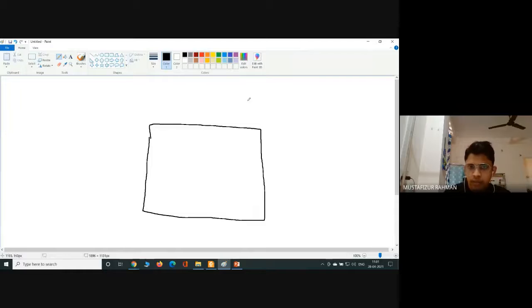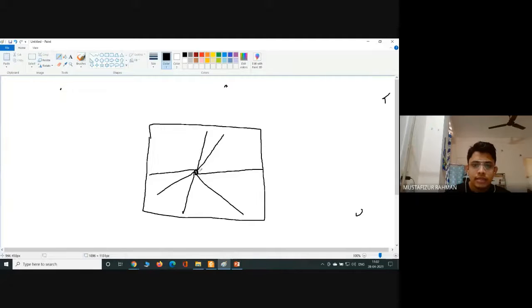If this is our plane table, we have different points along these directions. From the central station, we can go in many directions like this. Then at some suitable intervals, say for example at an interval of 4 meters or 5 meters or 10 meters, we will mark some points along these radial lines. Then we will measure the RL of different points along this line, like this.